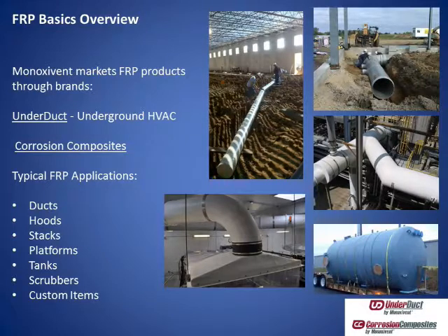For instance, you could take an ammonia or sulfur-laden air from a wastewater plant and run it into a scrubbing tower, and you'd have a bed of packing material that is wetted out with, say, ammonia, and it would take all of the sulfur fumes out of that as the air moves through it.